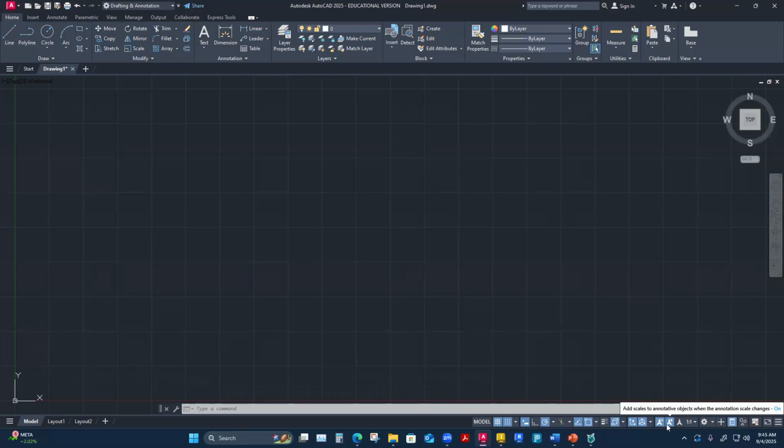Height is our text height. That's what we like to be as the finished product on our drawings. All of our dimensions should be 0.125 in height. Any text that I would have added to a leader line or a description of something should be 0.125. There are some reasons I would break that rule. If I have a big note that I want to stand out, I would double the size of that text to a 0.2 size. It should be 0.25, but I think ASME calls it a 0.2 size text. Double the size of a normal text size.